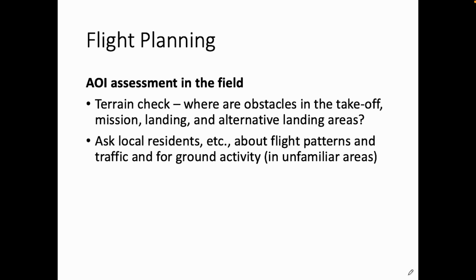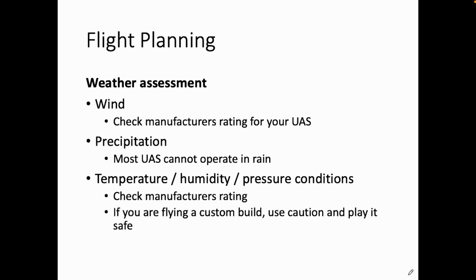And obviously you want to do your terrain check, look for obstacles, look for towers, and if you look at my videos on airspace charts, aeronautical charts, then that's going to help you with that assessment. You'll want to obviously check the weather. You're not going to be able to fly in the rain, most likely. You're not going to be able to fly in the fog. You're not going to be able to fly in conditions where you're outside the manufacturer's specifications for the UAVs.